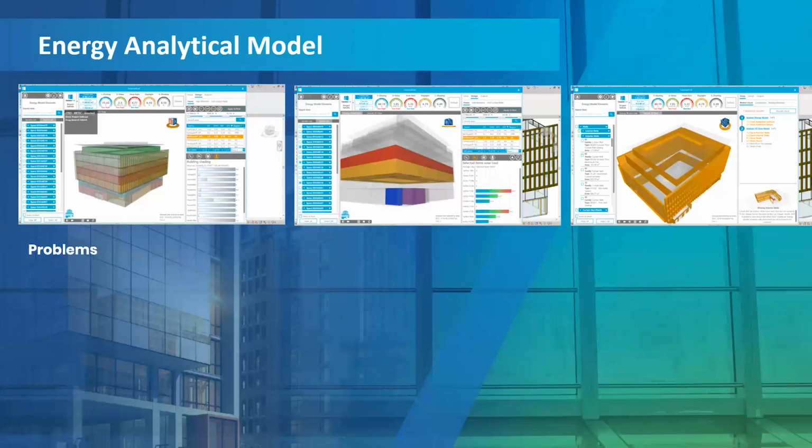Those drawbacks are, again, related to that energy analysis model. So some of those problems that we've seen over the past few years, and this is through direct engagement with some of those firms that they've spoken about, and users and customers of Fenestra Pro, they've been telling us that it's challenging, right? It needs to be a well-built model to generate correctly, right? Like, you need to know what's an external wall and what's an internal wall. You need to assign certain properties if there is glazing or not glazing or whatever. But the crucial thing is, when those things don't occur, it's quite unclear to the user.